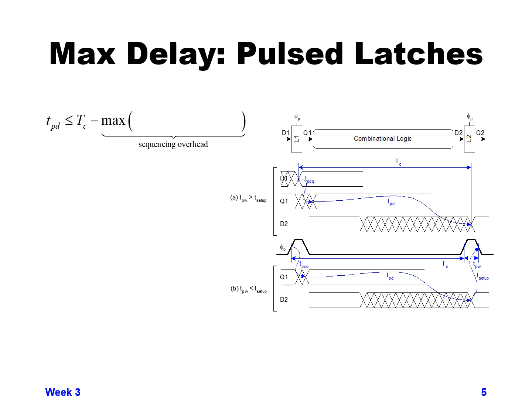So the last max delay example that we're going to look at right now is based on the pulse latches. Remember, we said there were three main types of sequencing that we do: flop to flop, two-phase latch design, or pulse latch to pulse latch, because pulse latches act similar to flops in behavior.